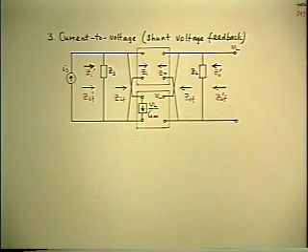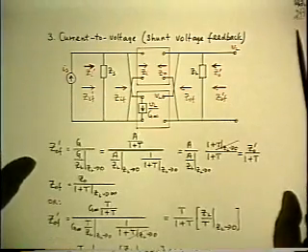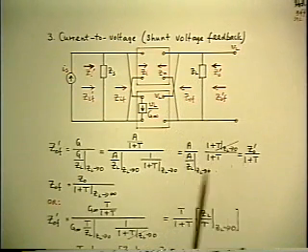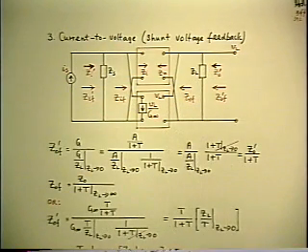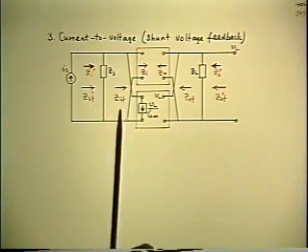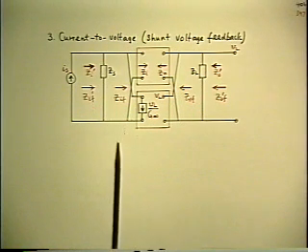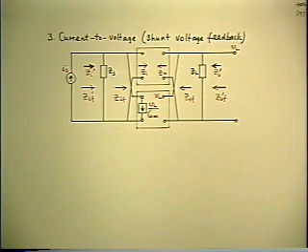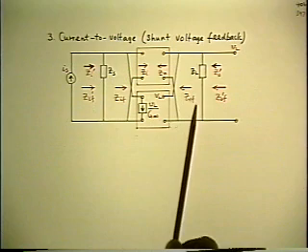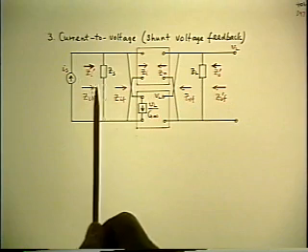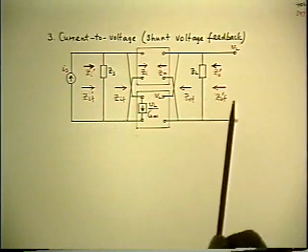And again, if I can find it, I can use exactly the same overlay. So there's the first one we have. Voltage feedback lowers output impedances. Okay, now what about input impedances? Now, once again, the input impedance formula was derived on the assumption that the input signal was a voltage, and now it's a current, so we need a new formula. But now, obviously, we do just the opposite from what we did at the output, because I've carefully drawn the configuration now to show that the input circuit is identical with the output circuit.